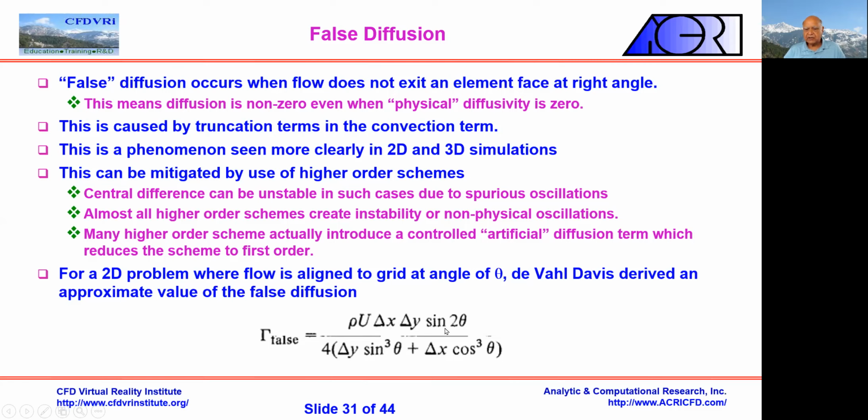So for example, at an angle of sine theta and large enough u, this can actually become larger than the actual viscosity you have in the system. I mean, it can lower your effective Reynolds number. I know of a square cavity problem, for example, where we solved it for a very large Reynolds number and it converged all right, but the solution was worse than that at a much, much lower Reynolds number. So this is one option.